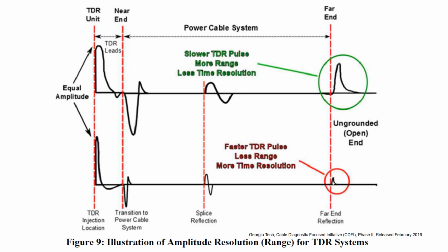So the problem here is this reduces the range of the testing. A faster signal can be used for small range, but with higher resolution. But a slower signal will work for longer distances of the cables. But you have much less resolution because the pulse width itself is more actually. Here the pulse width is small. Here the pulse width is more. This has just one giant. You can see very sharp signals like this. But here you see the one giant reflection is occupying this much space.